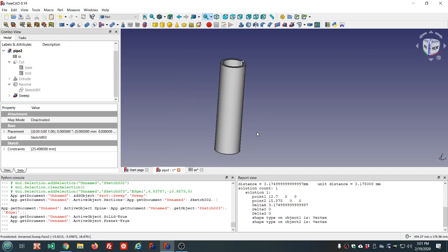You would use the revolve tool in this case instead of going through this trouble. But if you wanted an elliptical path, then you could use an ellipse instead of a circle, which would be not something that the revolve tool would support. Well, that's going to be it for today. We ran a little bit over long with 38 minutes or so, but we covered reproducing this pipe model using sketches in the part workbench.